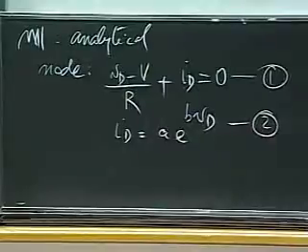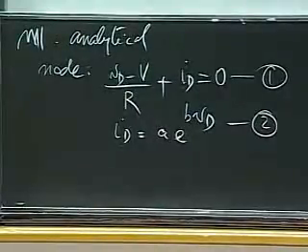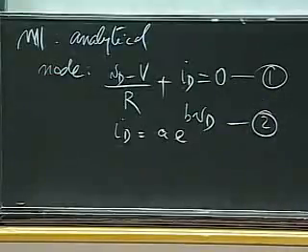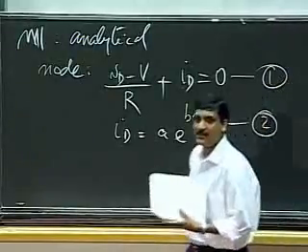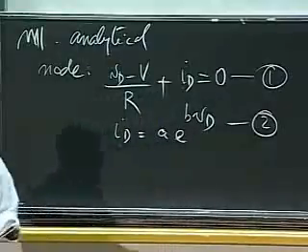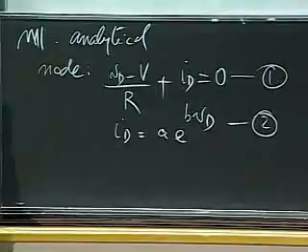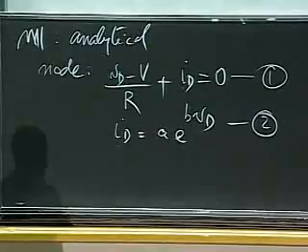You can now go ahead and analyze nonlinear circuits. You get a bunch of equations, a bunch of unknowns, and you go solve. I have two equations here. VD and ID are my unknowns, and I can just solve for them. Now, in general, with nonlinear circuits, oftentimes it's hard to get a closed form solution. So you may have to use a bunch of methods. You can try a closed form solution, or you can try numerical solutions, or you can do trial and error.